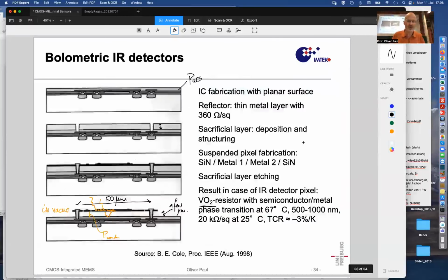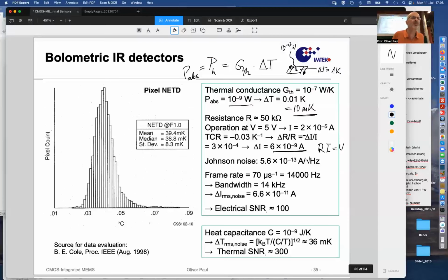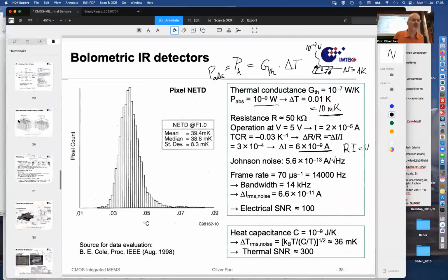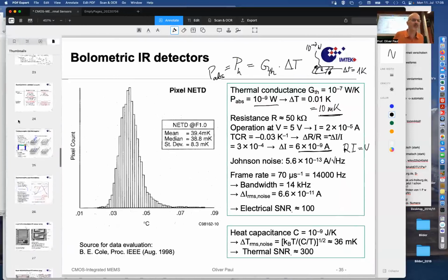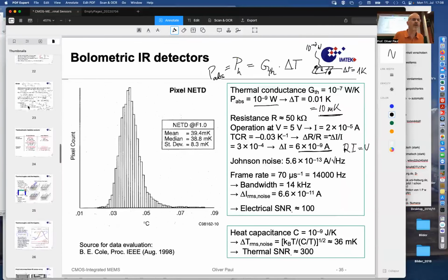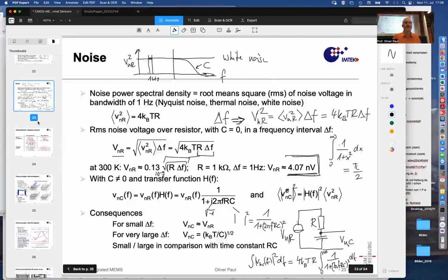So let me go back to these earlier slides. Do we have them? The noise slides. Yeah, we've had some formula. This one in particular. So if you measure the voltage of a resistor, it just stands out there without any other things. The charge carriers moving around will cause a voltage fluctuation. And that voltage fluctuation is described by this formula.